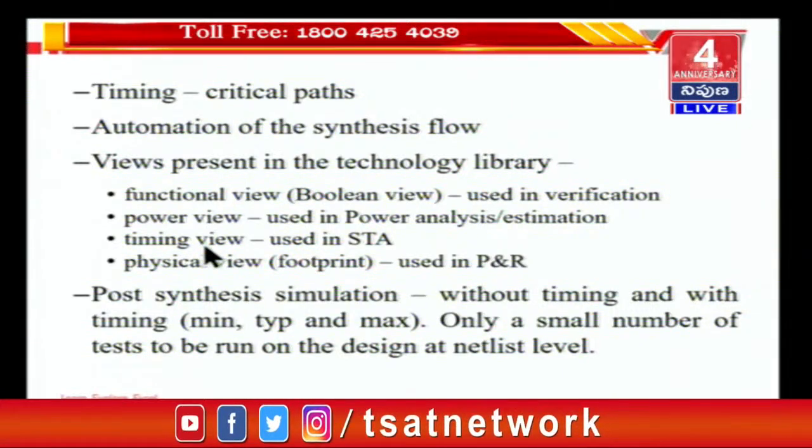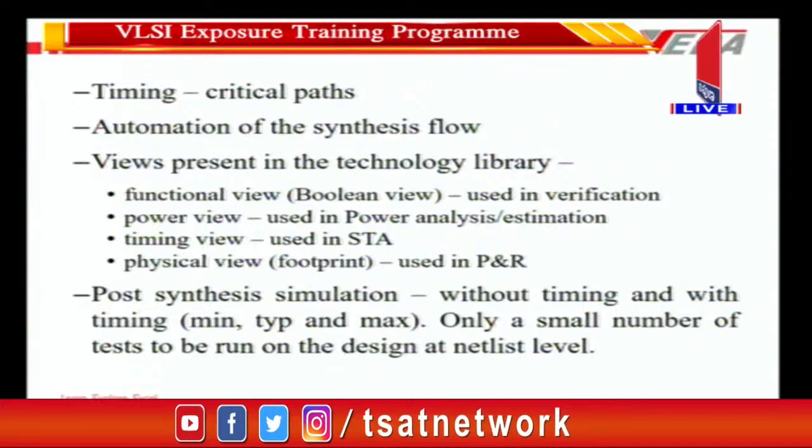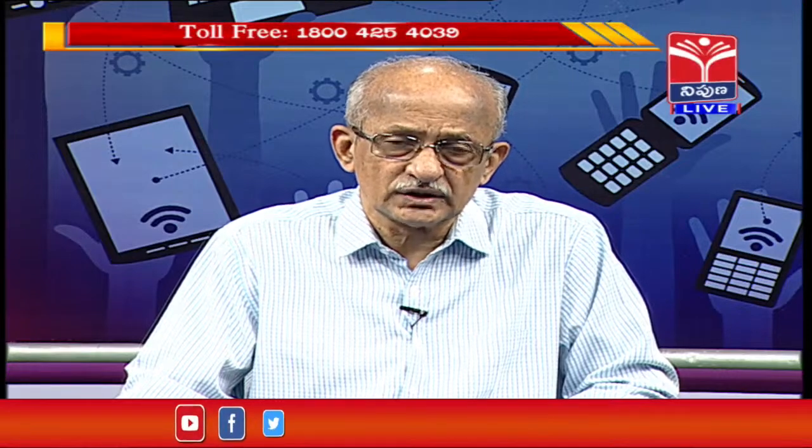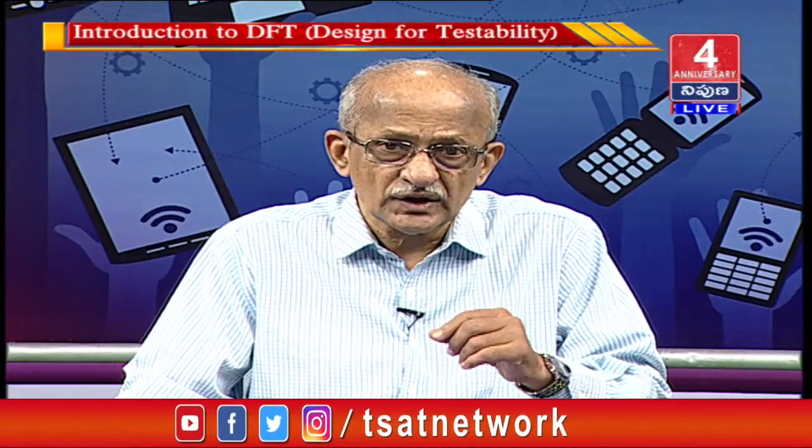for RTL level simulation. Therefore, all the tests which were run at the RTL level will not be run at the gate level. What the gate level simulation will do is pick only some representative tests from the RTL level tests that were run, and run them at the gate level just to give a degree of confidence that yes, the synthesis tool has properly converted the design from RTL level into the gate level. Now I am not saying that there is a doubt on the synthesis tool, but every transformation needs to be checked, because it is possible that you may have written the code in such a way that at